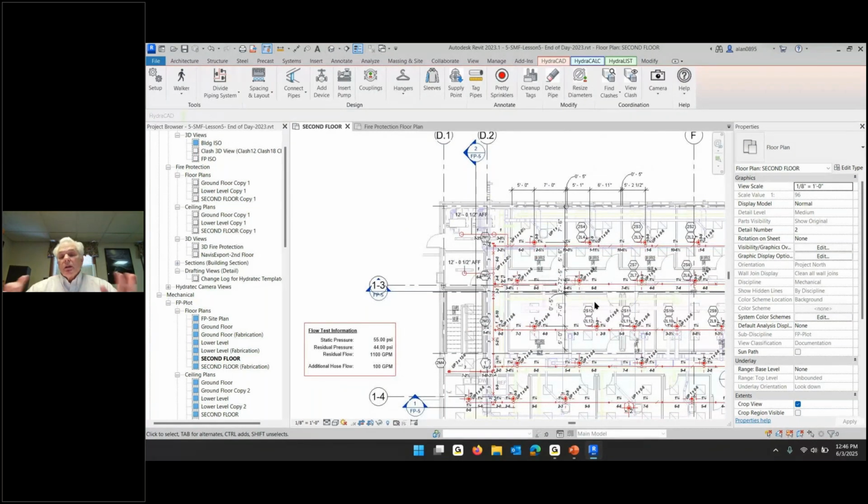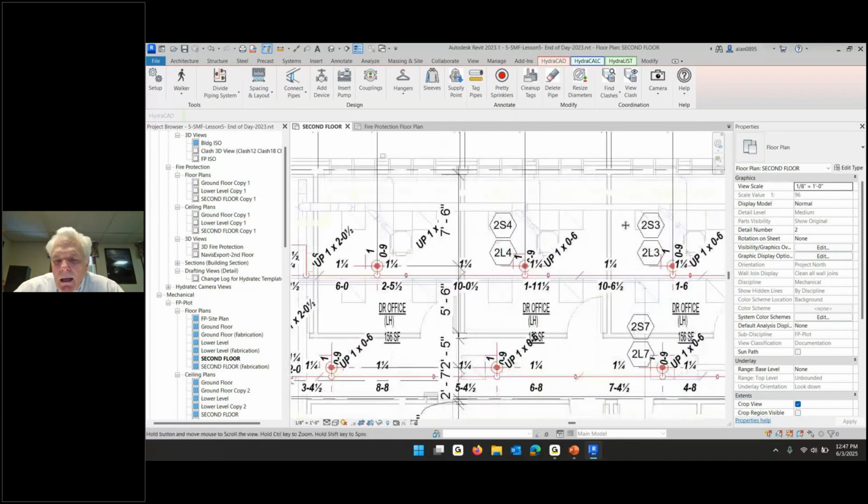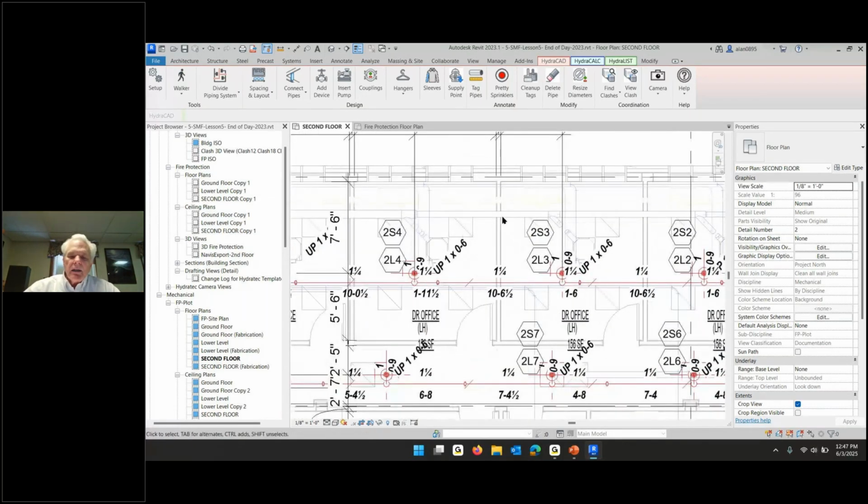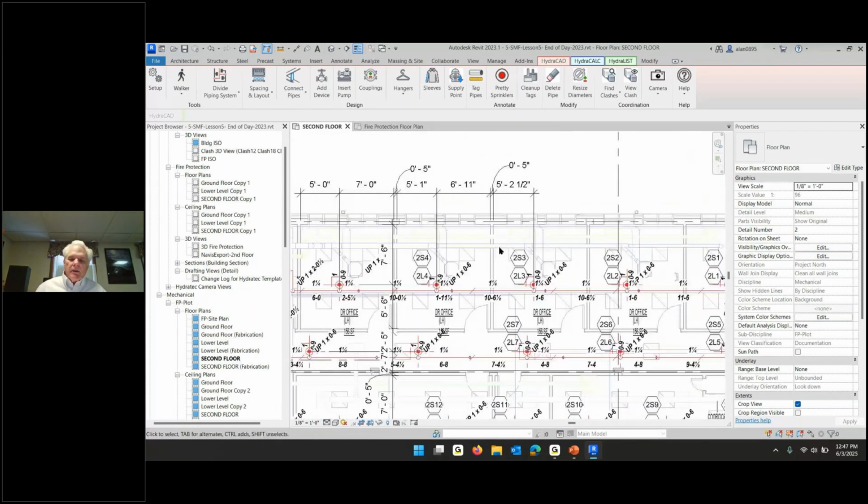Just a reminder, the one really big difference between AutoCAD and Revit as far as dimensioning is concerned is AutoCAD is basically dimensioning from a point in space to a point in space to a point in space. You can pick on something or on nothing, and it'll put a dimension. In Revit, you're dimensioning between objects. You must pick on an object. Once you've picked on the object, the align dimension is the best one for that, but you're trying to pick parallel lines to align to.